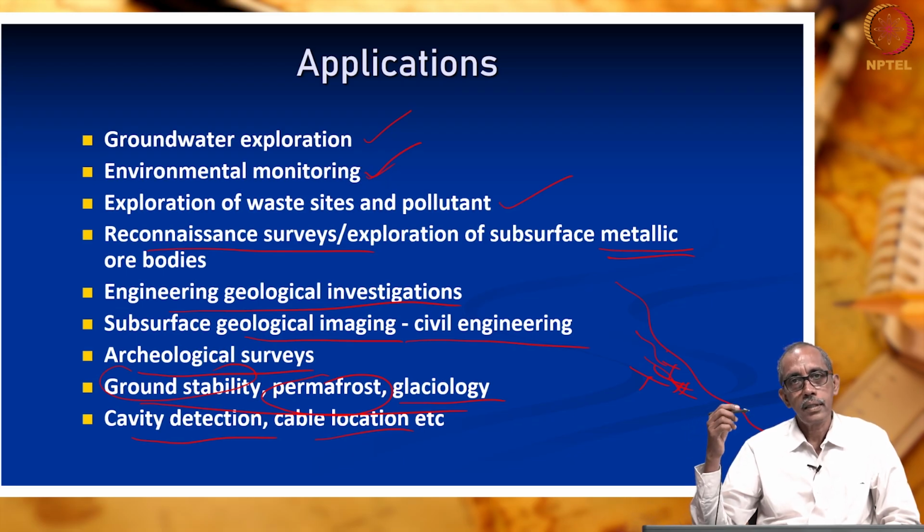So, in this lecture today, we continued our interpretation of resistivity data. We spent some time understanding the 4 classical types of resistivity curves which we are expected to get when we conduct a survey by vertical electrical sounding. After that, we devoted our discussions to 3-dimensional resistivity survey or electrical resistivity tomogram.